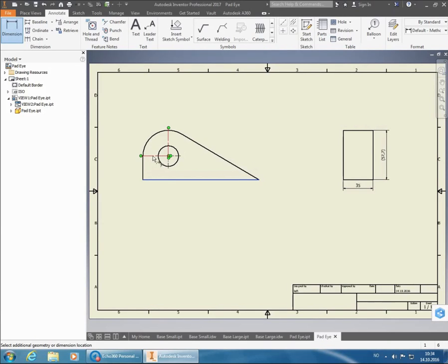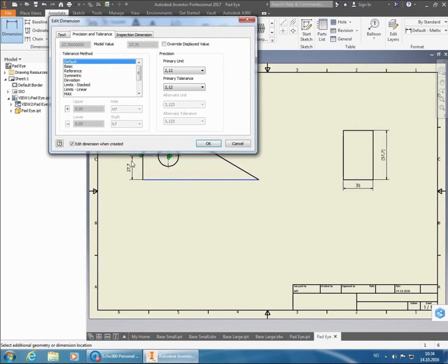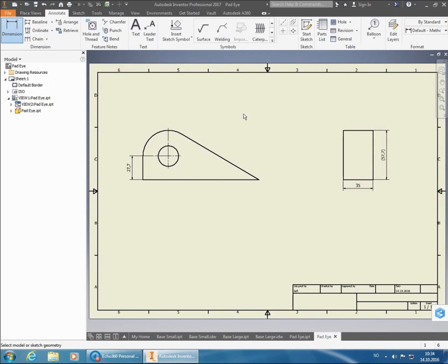So if we go from the baseline and up to the center point for the hole, those 27.7 millimeters will be defining the height along with the radius. So when they're creating this cut, if they're a bit off on their tolerances, it's going to affect the total height.